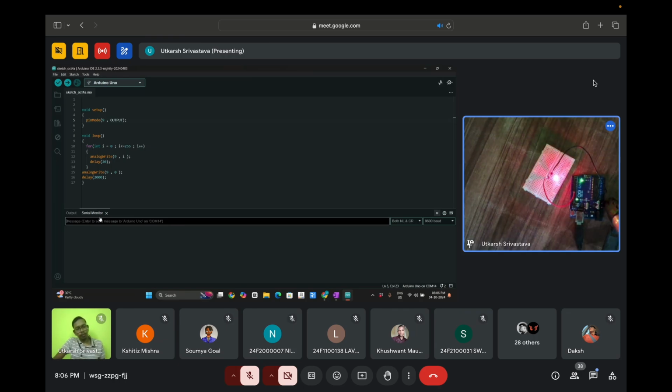So what we will do is send a command to turn this particular LED on and off with the help of our laptop. The code will not be the same; we have to make some changes. So let's see what we have. First, we will tell the microcontroller, hey microcontroller, we are using your UART communication, meaning serial communication. For telling the microcontroller, the function is Serial.begin.